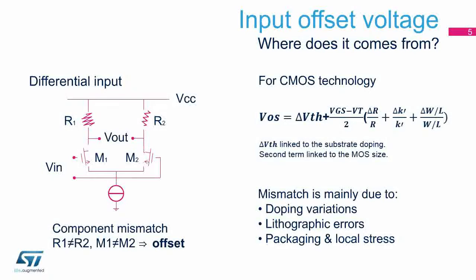Thankfully, this never occurs in practice. They never cancel each other out either. In any case, regardless of the design or process effort, there always remains a small input offset voltage. This also explains why for a dual amplifier, where 2 op-amps are in the same package, the input offset voltage of both channels is different.